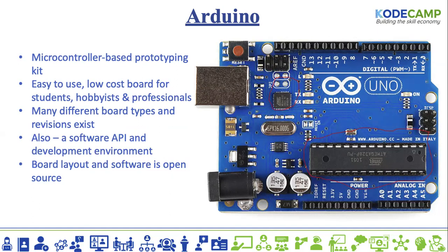It has the crystal oscillator, and this is for power, this is for reset, and these are the GPIO pins. We talked about GPIO pins, and these are for the onboard power. Like if you want to get power from it to another component, you can choose from here. Or these are all the analog pins.